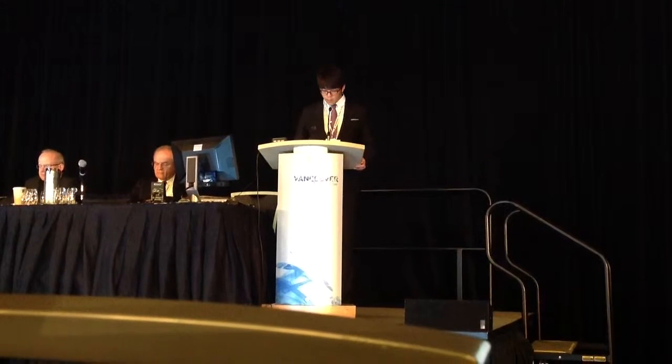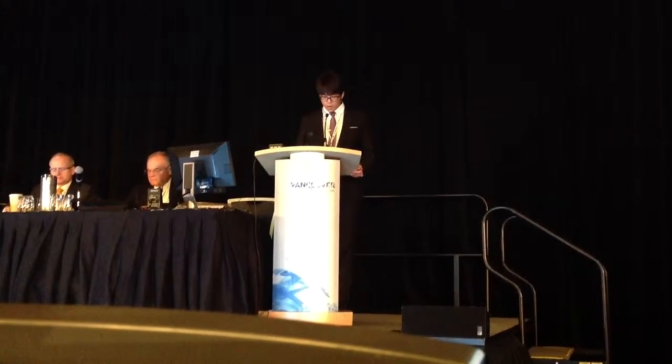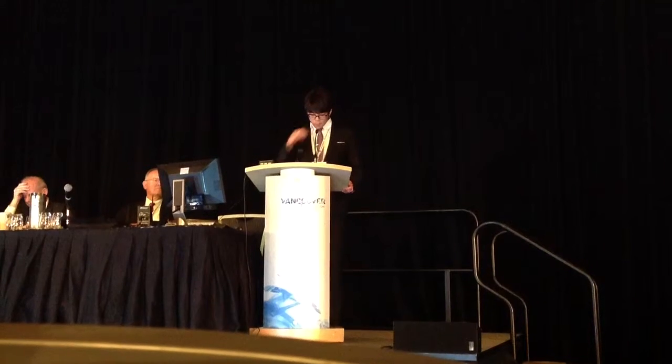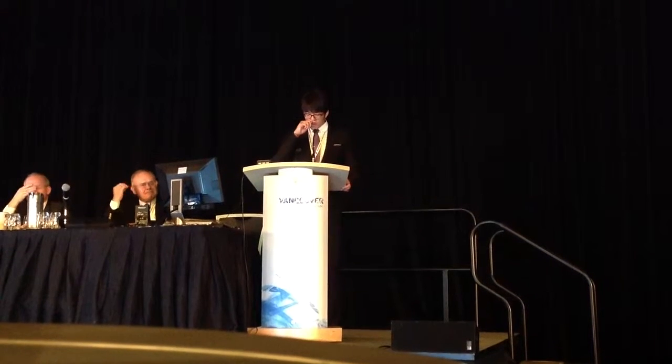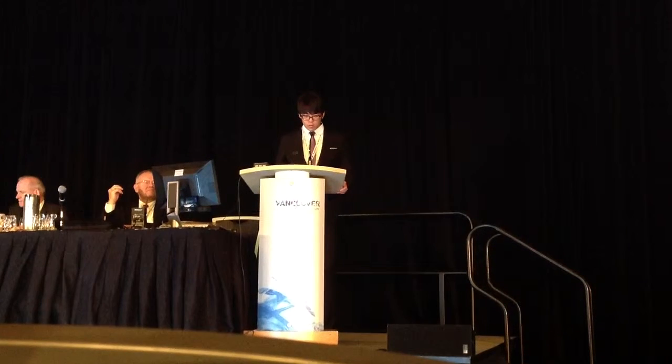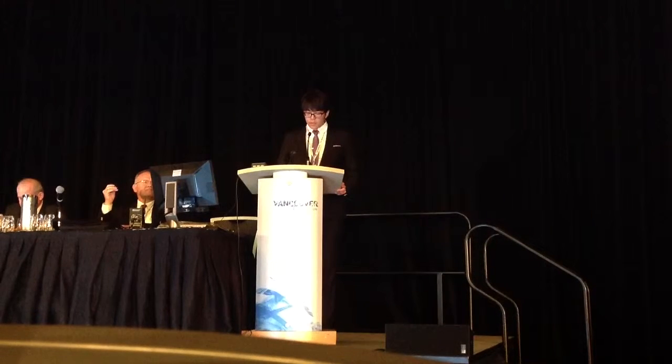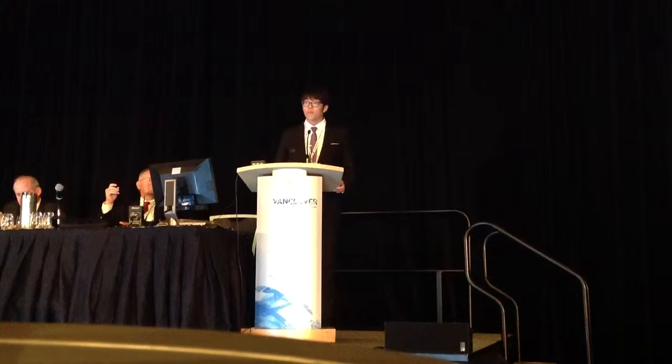However, there are some problems in LCDs. Among them, I'd like to focus on two main issues. One is the short gate turn-on time, and the other is the heavier electrical load of gate and data lines. As shown in this figure, the higher the frame frequency and resolution become, the shorter the gate turn-on time is. So, an optimized driving scheme is necessary for these ultra-large size, high resolution, and high frame rate LCDs.